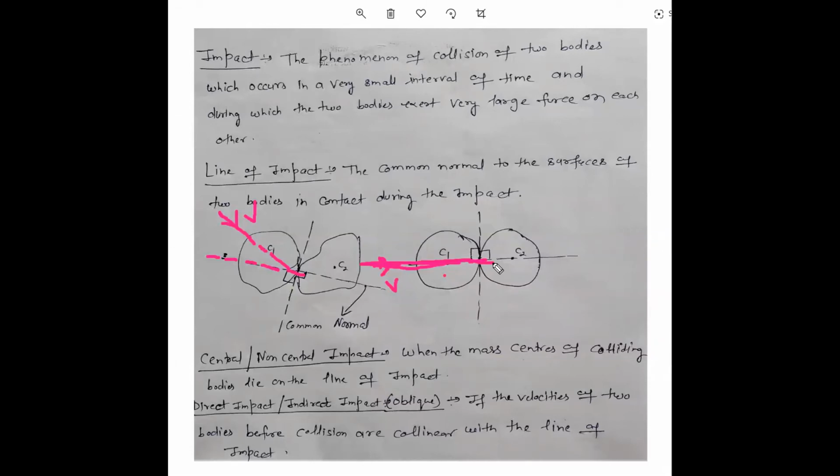तो जो वेलोसिटीज हैं, ये कांटेक्ट बनाने से पहले की देखनी हैं, कि what are the directions of that particular bodies before the collision, हाँ, before the collision, ठीक है। दोनों वेलोसिटी होनी चाहिए, ऐसा नहीं कि एक वेलोसिटी। For example, this body is coming from this direction, so at this time we don't call it a direct impact, we call it an indirect impact, or the second name of indirect impact is also known as oblique impact. Oblique means the angle is greater than 0 degree. यदि आपकी velocity vector और लाइन ऑफ इम्पैक्ट मर्ज कर जाएंगी तो एंगल कितना बनेगा, 0 डिग्री बनेगा। और ओब्लिक का मतलब क्या है, कि एंगल is greater than 0 degree, जहां पर एंगल बन रहा है वो 0 डिग्री से ज्यादा बन रहा है, that is known as oblique.